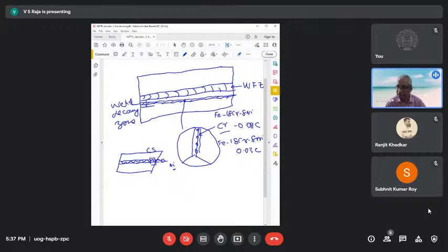Now let's go to applying a paint over zinc. People apply paint over zinc in order to increase the corrosion resistance. Then what is the purpose of zinc? The purpose of zinc is, should the paint coating fail, the zinc coating should protect the steel surface by sacrificial action. That is the whole purpose of applying zinc coating on the metal surface.